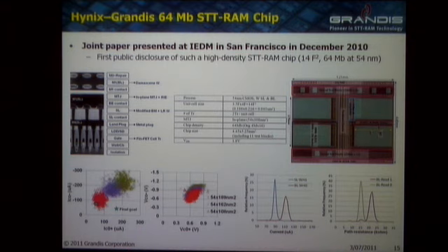So once we go to the dual MTJ device with Hynix, this should come down by a factor of 2, and this will come down by close to a factor of 2 as well. So the net result of this is, if you just look at this resistance distribution from the chip on the right here, the green is the low resistance state, the red is the high resistance state. You can see not all of them are switching. It's about a 95% switching yield.